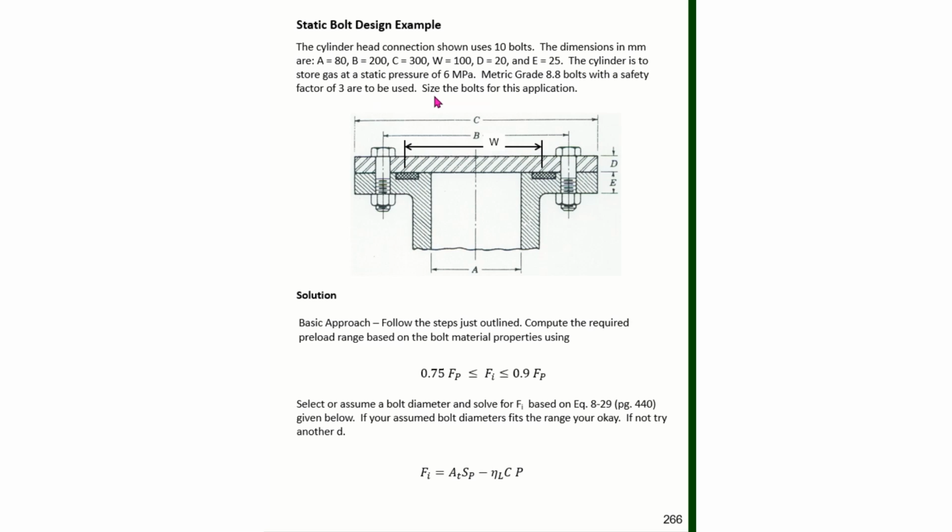One of the things that we need to consider first is the force in the bolts. And we need to determine that force by understanding the pressure loading from the cylinder cavity. Looking at this, we know that this dimension A has an internal pressure that's pushing out on this top cap and the cylinder head.